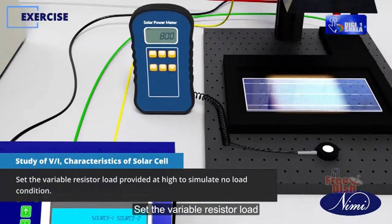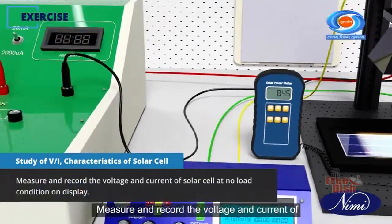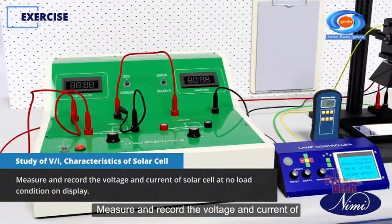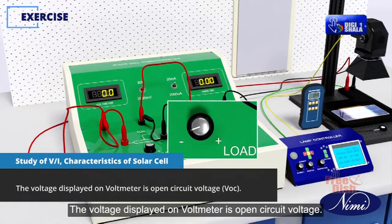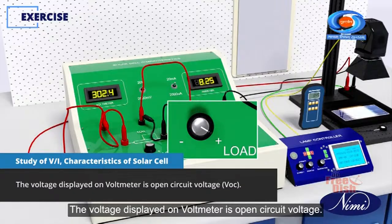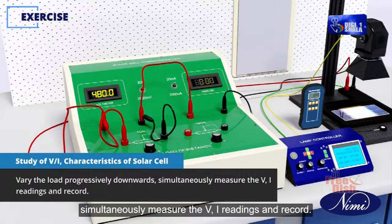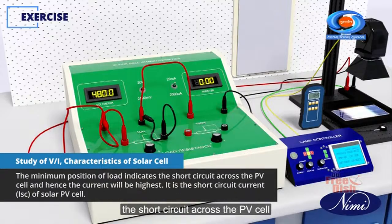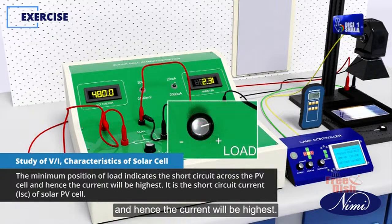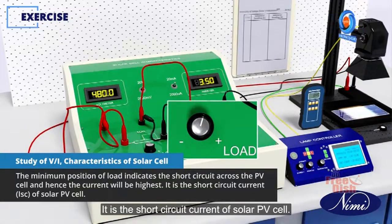Set the variable resistor load to high to simulate no load condition. Measure and record the voltage and current of the solar cell at no load condition on the display. The voltage displayed on the voltmeter is the open circuit voltage. Vary the load progressively downwards. Simultaneously measure the VI readings and record. The minimum position of load indicates the short circuit across the PV cell, and hence the current will be highest. It is the short circuit current of the solar PV cell.